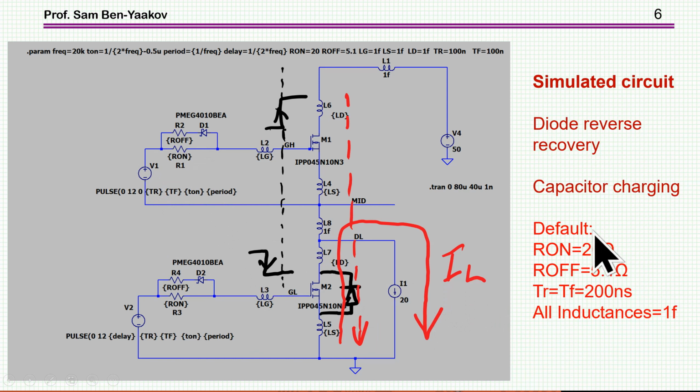Now what we have here is the transistor with its internal inductances. This LG actually will represent both the internal and the external inductance of the line feeding the gate. And then we have a bus inductance, which again the default value is 0 as a matter of fact.